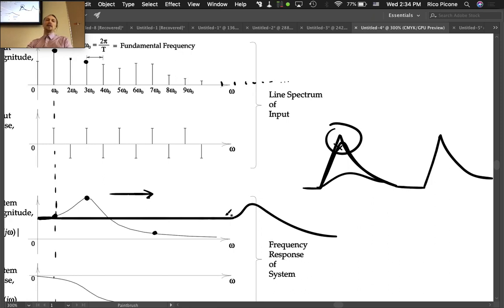Now, another thing you can try is, you never know. There could be, it's rare, but there are situations where you're going to have an input signal that's got some stray high component, high magnitude, way out at some high frequency. That's possible in your measurement signal. But you're going to have to just at some point say, I'm going to ignore any frequencies higher than this cutoff, and you won't capture them in your measurement. So they could be there. You can't rule them out in your measurement, but you also can't move this out indefinitely. Every measurement system's got to have a roll off somewhere.